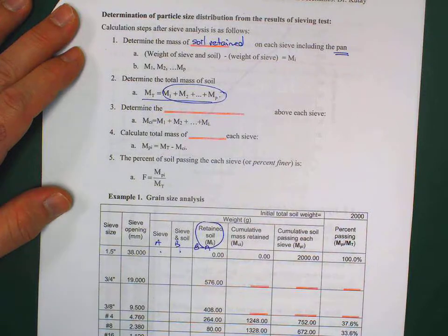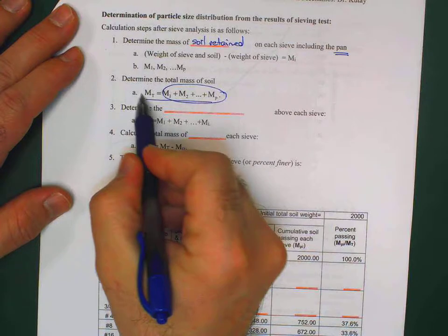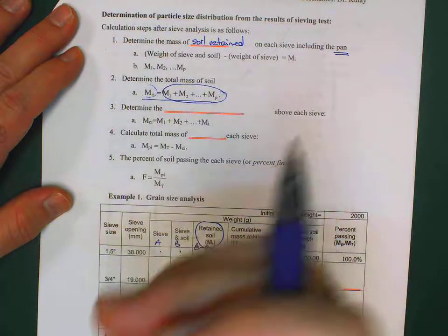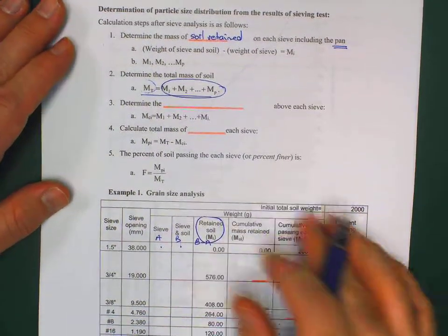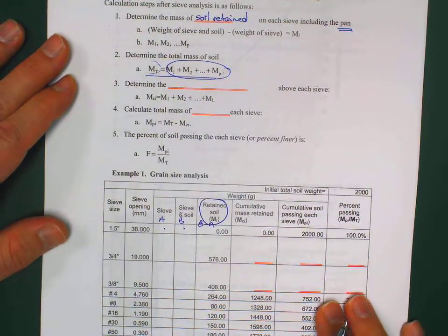Or it's going to be 2,998. If you get 2,500, well, you need to go back and check your calculations, or maybe you missed one sieve or something. Okay? So you need to make sure that these match. Actually, according to the standard, if there's a difference that is more than a certain percentage, you have to rerun the test. Your sieves need to be clean and all that. These things are important. They are simple, but they are important.